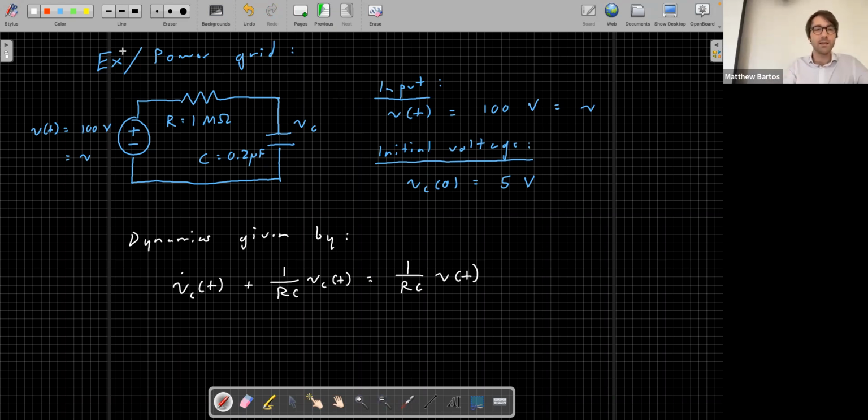So let's go ahead and take the Laplace transform of this entire differential equation here. What do we get when we take the Laplace transform of the first derivative of the capacitor voltage? S times, right, so we'll get S times Vc of S. Is there something else we need to consider? Right, minus the initial condition, which is vc of 0.